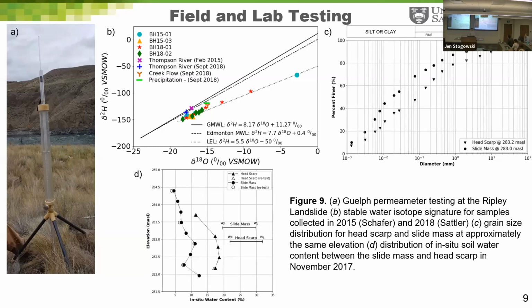So during the field program, in situ testing was conducted for the saturated hydraulic conductivity of the superficial till material using a Guelph permeameter. Although the results are only valid for discrete points, the 6 tests gave surprisingly consistent hydraulic conductivity estimates within 2 orders of magnitude. Samples collected during the hand auger drilling and water samples from local precipitation, runoff, and the river itself were analyzed to determine the stable water isotope composition. These water isotopes verified that the groundwater originated as cold weather precipitation and runoff.